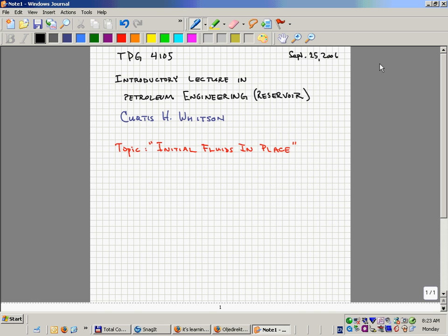If you have 1 millidarcy, which is probably what this is, then you have to work at getting the fluid flow to move. So you have to have big pressure gradients. You have to either push here and pull here, or like Ekofisk, you've got 7,000 psi, pounds per square inch, so about 450 bar initial pressure. And so you put a pressure at the producing well of 100 bar, and now you've got a driving potential of 350 bar.